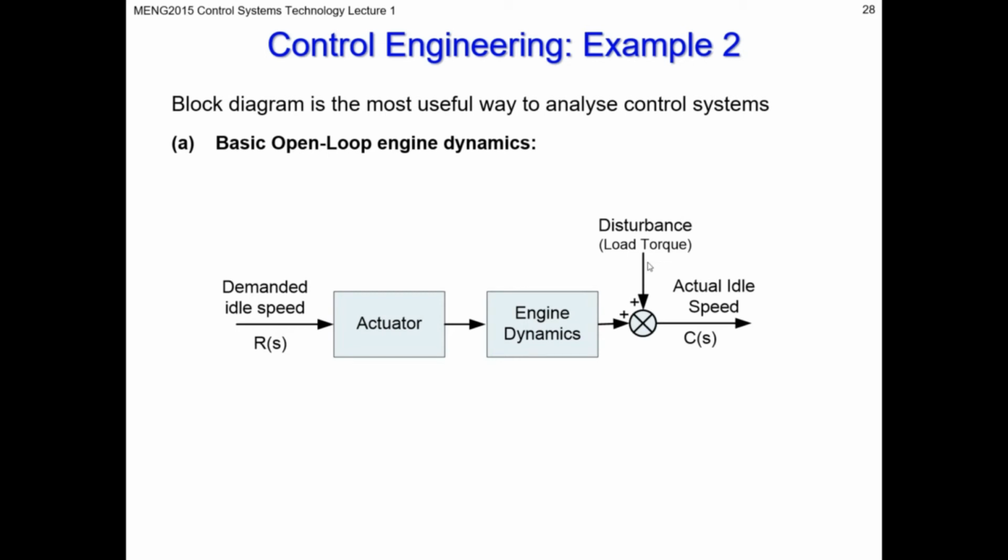It's actuated by a clutch, so when the compressor needs to turn on and the clutch engages and starts to spin up that compressor, it puts a big load on the engine, especially when it's at idle. That would pull torque out of the engine, and it would want to slow down. In a sense, it increases the effective inertia of the engine, and therefore will try to slow it down. So you end up with an idle speed after the AC turns on which is lower than the demanded or set point engine speed, and there's nothing much you can do about that.